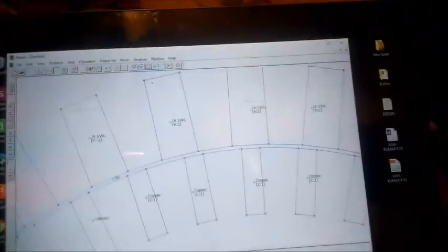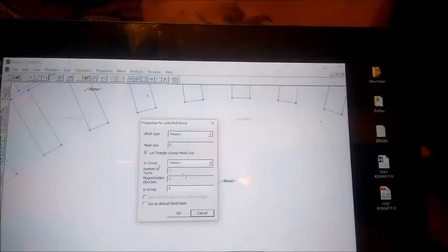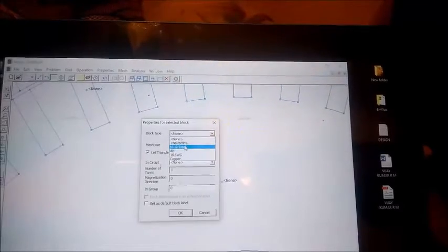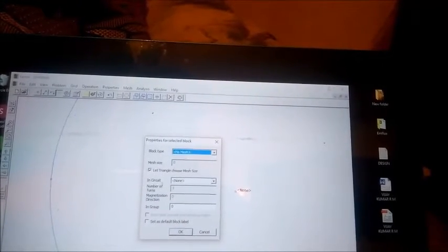And also just add the rotor core material, that is magnetic material. Just go to M19, add it, okay. And for here, this is a shaft position, so just choose no mesh. You can choose any material, but it's preferred, whenever we don't use it, to choose no mesh. And you can create a mesh.